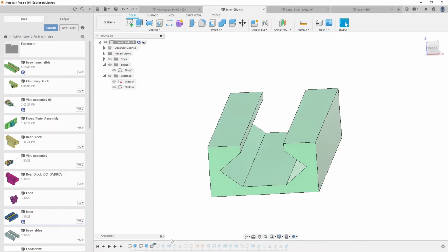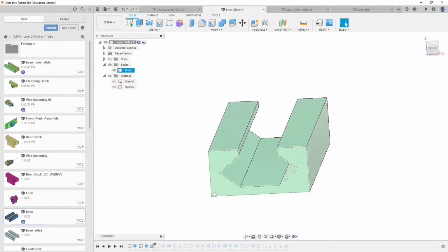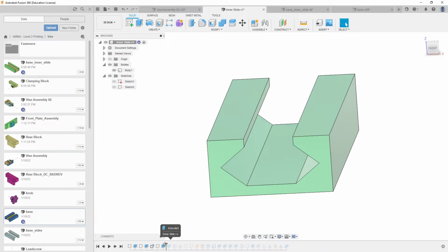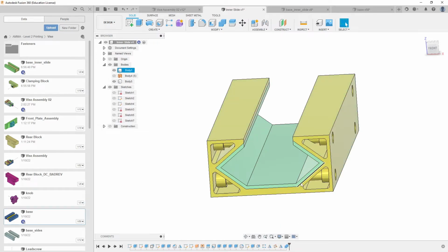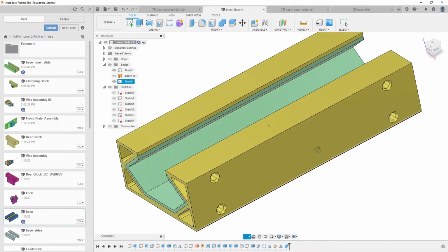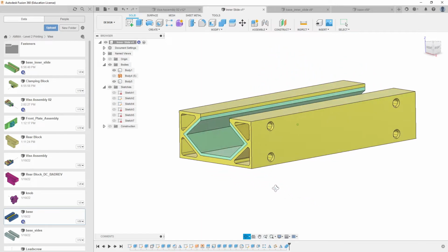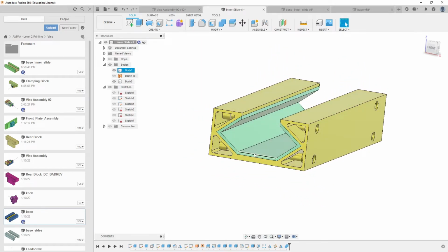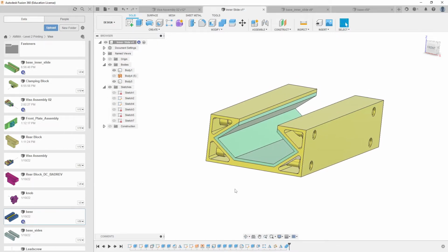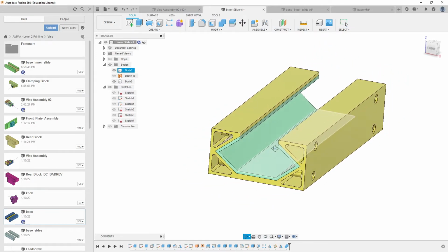And, you know, check your work along the way. Nothing in the widthwise here will be a problem in the future. So then you roll it all the way forward to make sure nothing has an error. And if you had something that had a blatant error, you would see something yellow down here. Maybe something would pop up over here to tell you. Examine everything. Make sure that you think and believe that everything is working the way it's supposed to. Maybe take some measurements and such to see if it still fits. Maybe bring in the other elements if you had made some of those already to make sure nothing is clashing. But all looks good.